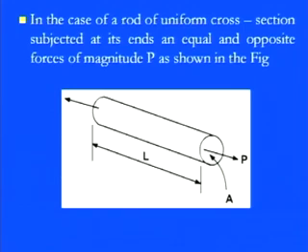After going through this internal energy, we have a clear feeling that whatever the load application is, as in the diagram in front of you, we have equal and opposite loads. So we know P. Once you know P and the cross sectional area A, you have the stress components. You know the material property, so you have the value of E. So sigma x square by 2E, and then the domain of this element: if it is a cylinder, or the cross sectional area is a square or any rectangle, simply take the volume of that and calculate the strain energy of the whole element.